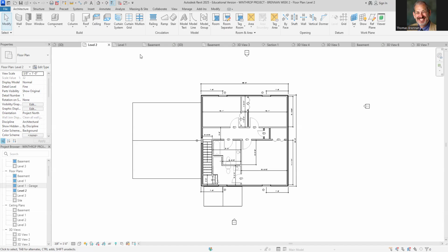It's on the correct level. Yeah, Audrey, you just need to go to the properties and put it on level 2. Yep, that works. Good. Properties is, yep, there you go. And then change the roof pitch to 4/12. Yeah, you too there, Ben. You want to grab your roof and change the roof to be on level 2. So go to your properties and change it from whatever it is right now to level 2. There you go. And change the roof pitch to 4/12. 4-inch, 12-inch roof pitch, yep.